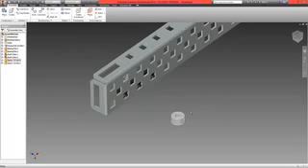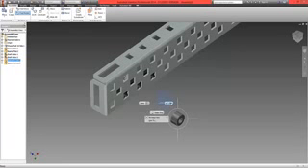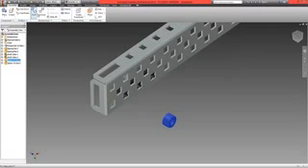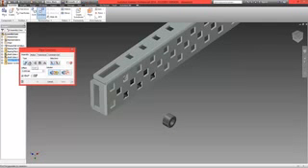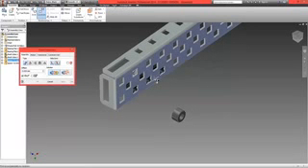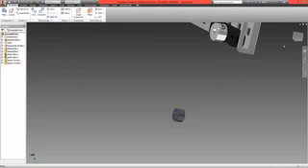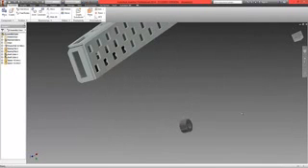To rotate your spacer to the right position, select Free Rotate from the ribbon, click on your part and drag and rotate it roughly into the right position, and then right click and select OK. What we're going to now try and do is position this to sit directly in line with this position here. Choose Constrain, and this time we're going to first of all choose Mate. I'm going to choose the top surface of the chassis, rotate around and choose this surface of the spacer, and select OK. What we've now got is a spacer that will sit onto that surface but not located.